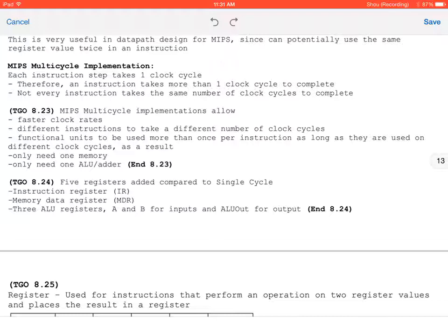Data memory: if it's a store word instruction, it's going to put the value to data memory, which is our non-volatile, slower memory in the cache hierarchy. Or if it's load word, we get that from the data memory, and then we'd be putting it back into the faster registers, which we'd use for faster instructions because we're trying to take advantage of the principle of locality. So that's a very brief overview of 385.